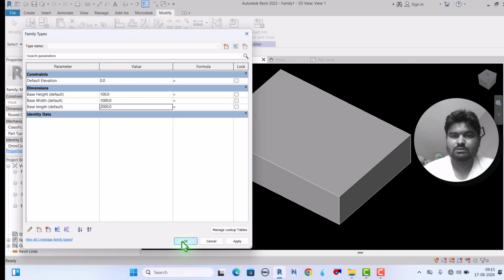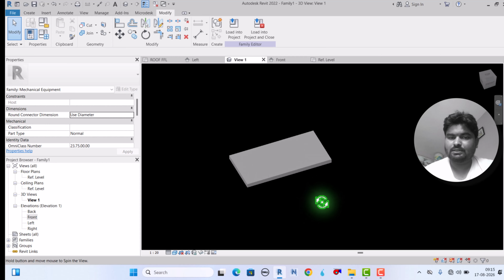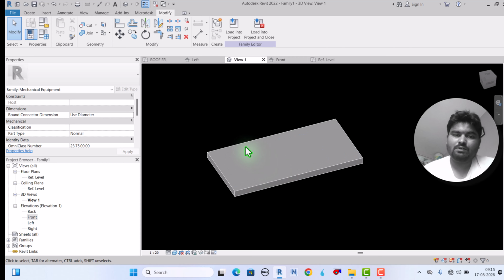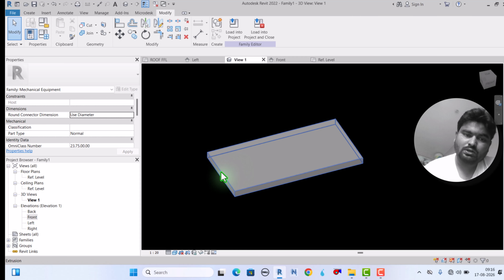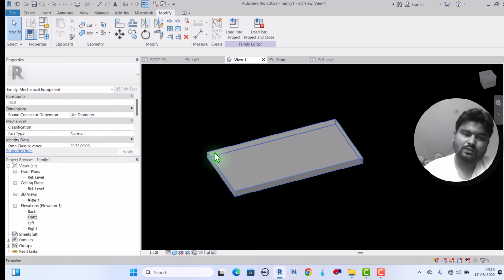Is it working or not? Yes, it's working, fine. So you can use this base to place our equipment, but I want a 200 offset on all sides, always fixed. Suppose I place our equipment here, then 200 space will be there for the maintenance guy to keep their tools and do the maintenance, okay.